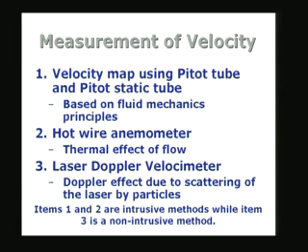However, in the case of laser Doppler, the laser beam itself is not going to disturb the flow significantly, and therefore, we can say that the laser Doppler velocimeter is almost like a non-intrusive method. So, the three methods I have labeled here. The first two are actually probe techniques, because we are going to introduce something into the flow, and the third one is a non-intrusive technique, where only a light beam or two beams of light are going to intercept the molecules of the fluid which is flowing.